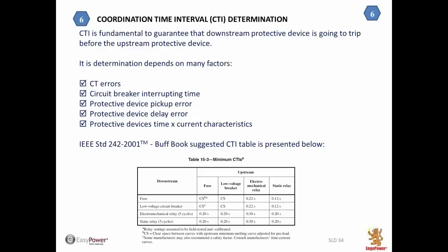Normally, what I could see testing the relays is that when the relay is directional, has directional elements, the time to calculate the direction is higher. And normally, one relay that calculates until it trips an overcurrent relay takes about 32 milliseconds to do this. When the directional element is used, it would take about 72, or in other words, about 30 to 40 milliseconds more. So we have to discuss this table a little bit more.